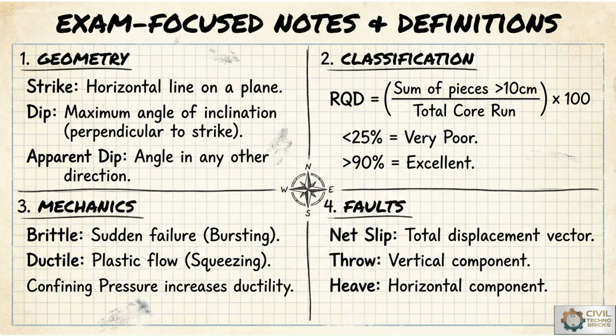So preliminary geological investigations are most important and essential for safe and economical tunnel construction. Understanding the rock patterns, such as based on the strike, dip, apparent dip, properties, structural defects, and groundwater conditions, improves tunnel stability.